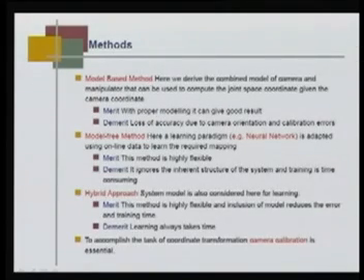Model free method: here we do not assume any model of the camera. The output is taken simply whatever U1 and U2 are, we really do not correlate that to what XYZ is, there is no need. But based on that we learn using the Kohonen based self organizing map how to reach the target.